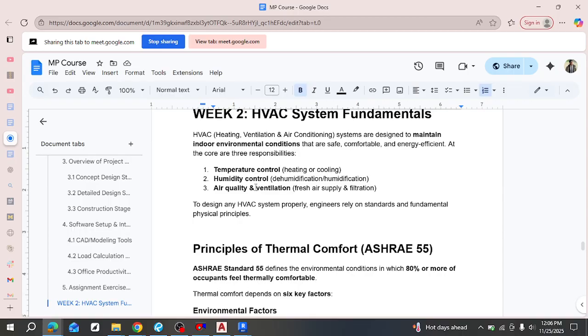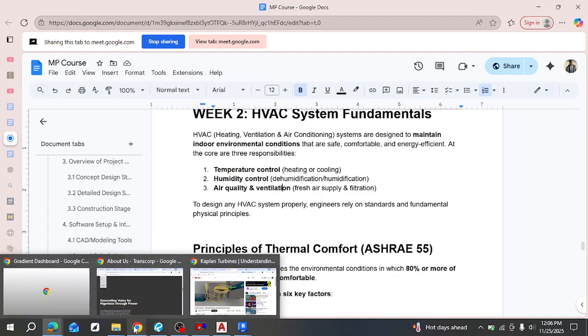So if it's a place where the air quality drops very fast, it needs to have very high ventilation rates. So that's why in some of your designs or in some air conditioning systems, you have some standards that state that a certain percentage must be outdoor air entering. There are even some equipment that are specifically for outdoor air. There's this one they call DOAS. Let's see. You can look it up at your end.